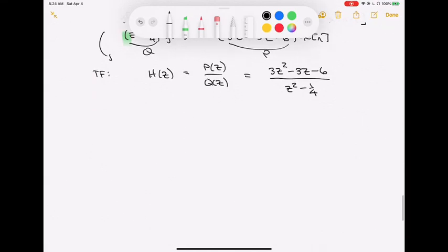Now, if I asked you in this particular case, give me the best, as far as what we've introduced, realization of this as a single stage best realization. What would you do? What is the best single stage realization? Well, we've already looked at that, right? We know the thing that makes us double happy is the transposed direct form 2 would satisfy that bill.